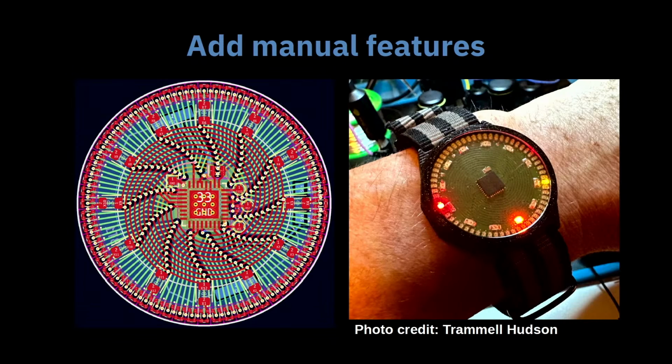And then he has a little microcontroller on this. So for the microcontroller part, he did that in KiCad normally. So he drew a little microcontroller and connected it up to the names, and then dropped some parts in. And then the way that works is Circuit Painter generates a KiCad file that has a group of all of the parts that it made. So you can either edit that file directly, or you can just copy that group into a new KiCad project, and then add your own parts.